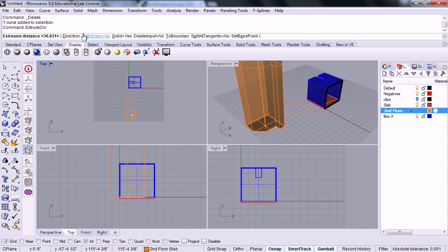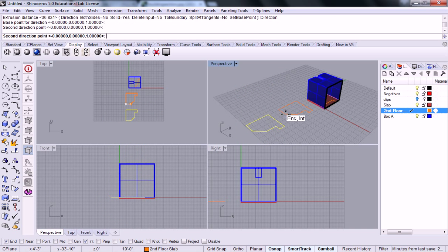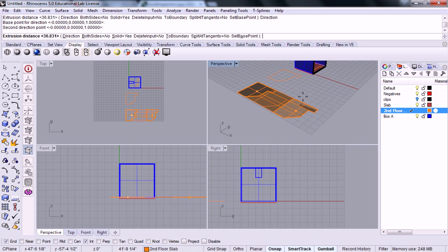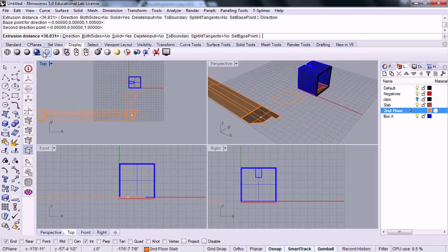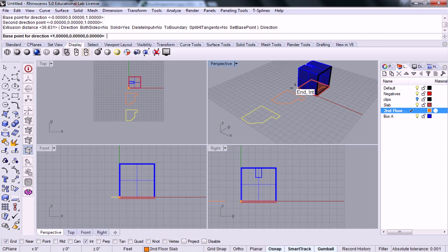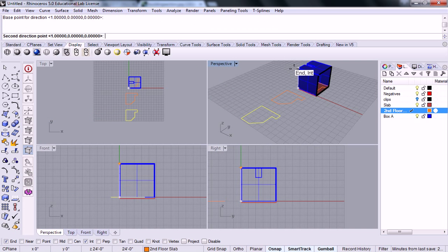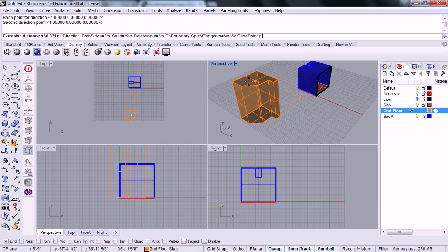If I accidentally was extruding sideways, this actually happens quite often, where you'll find that you accidentally locked on to the wrong direction here, kind of going along a plane. If that happens, all you have to do is just click on direction, find your model, and go from one edge to another that you know is in the right direction, and it'll go back. Does that make sense?